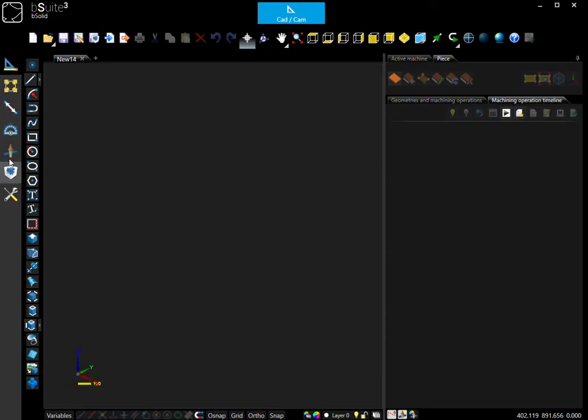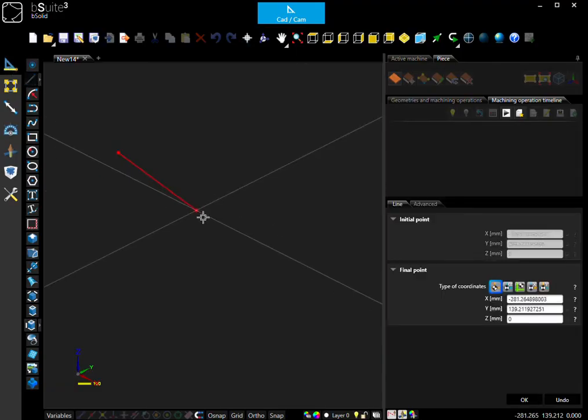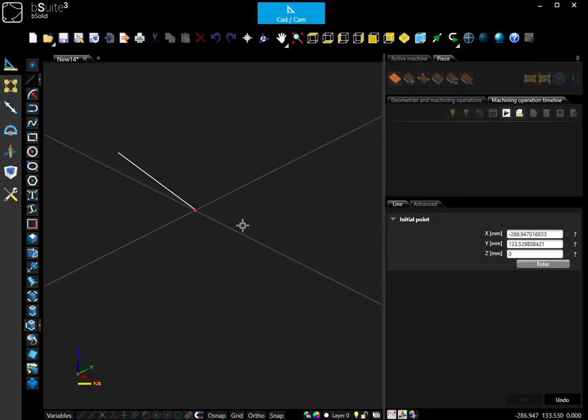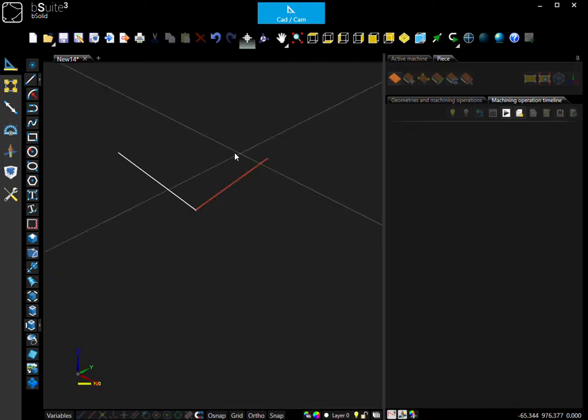Over on the far left here, we've got our 7 main toolbars that we can select between. So from the top down, we've got our drawing toolbar. When you click on drawing, it'll bring up this second one, which enables you to start creating geometry there in your drawing and geometry window. Hit undo when you're done to back out. Once you've created something, you can then modify. In here, you've got 2D drawing tools and down the bottom, 3-dimensional creation tools. Drawing and creation tools, so you know how to create surfaces and different types and ways and methods of creating surfaces.